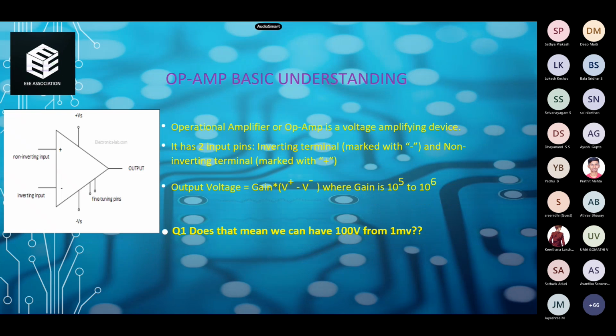Now, the op-amp is the most basic block which is used in the DACs or the ADCs. Op-amps are linear devices that have the properties of nearly DC amplification and are extensively used in signal conditioning, like filtering, or to perform mathematical operations like addition, subtraction, integration, and differentiation. That is where the word operational comes from, because it is used to perform many mathematical operations, whereas this is the amplifier. Basically it is a DC amplifier, and this is the block.